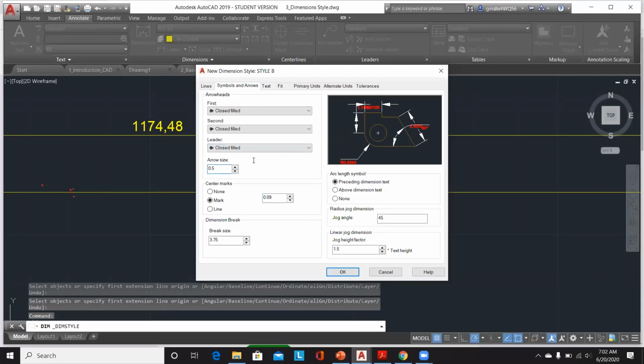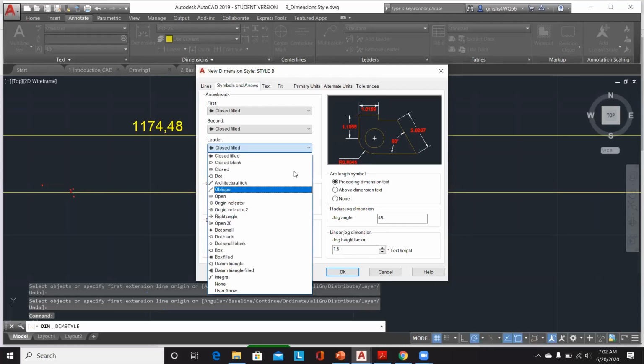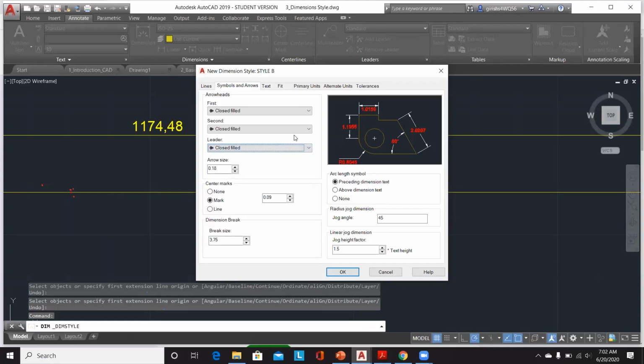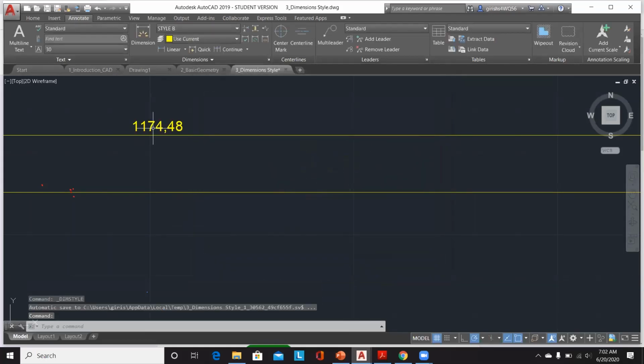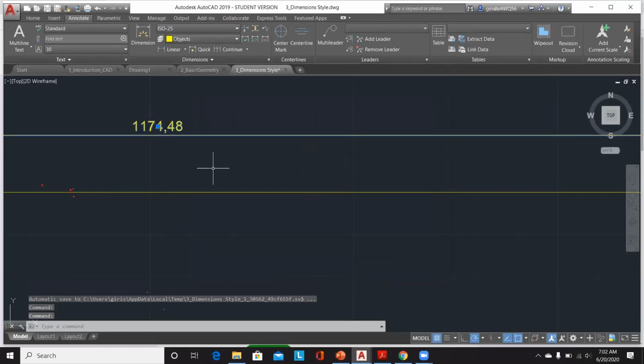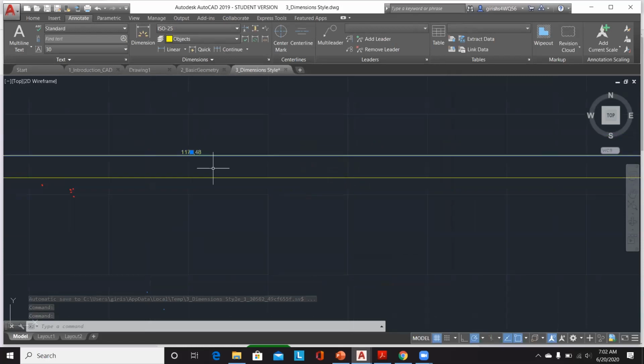So you can control the view settings and styles either based on a standard, like the Indian standards have provided, or you can decide it yourself. If you are a designer or a modeler and you want to govern it based on aesthetics, you can create those standards in AutoCAD and then use it as the current dimension style. So as you can see, my current drawing is in ISO 25, and I have added dimensions in it, helping me to create these drawings.